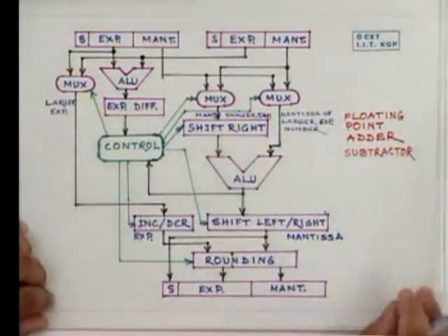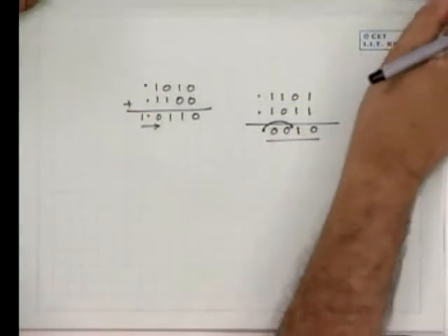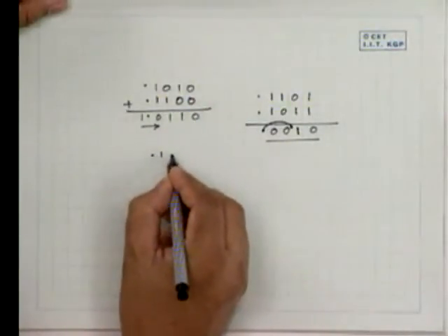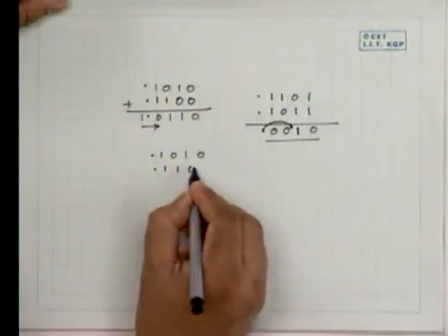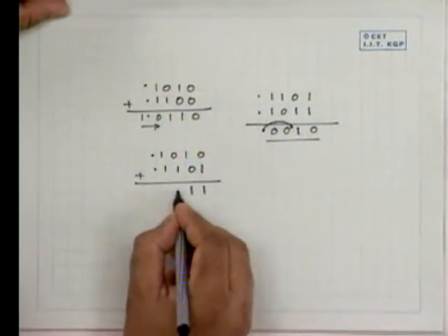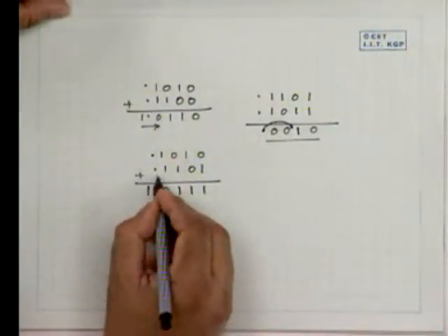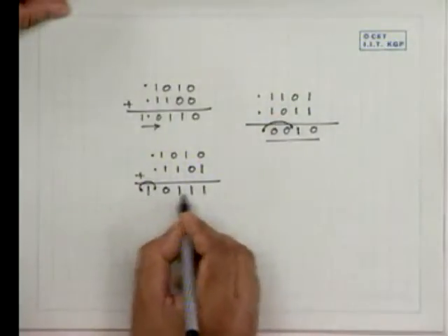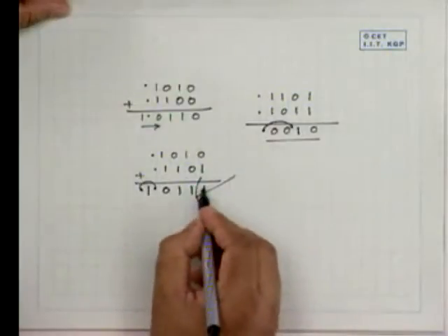And the rounding is done this way. So for example, you have to shift out. Instead of this, had this been 0.1010 and say 0.1101, and if you're adding, in that case this is 1 1 1 0 and 1, and the binary dot is here, which has to be shifted to this place, and to represent in the 4-bit representation, we'll have to naturally discard this 1 bit.